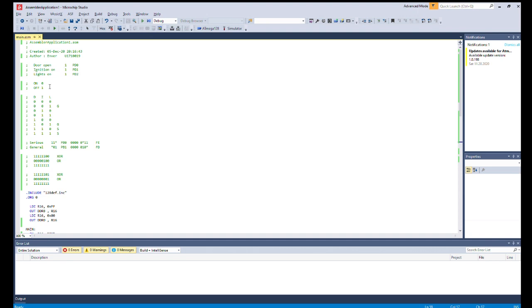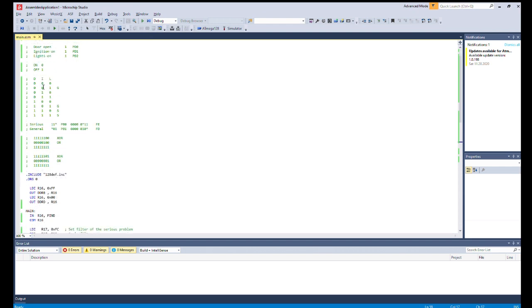Then we agree on the fact that lights is on if it's 0 and it's off if it's 1. Further, we will see that it's crucial to identify this in order to analyze the whole system. Then we proceed to the truth table. We can see here door, ignition and lights, and the last column is for the condition.